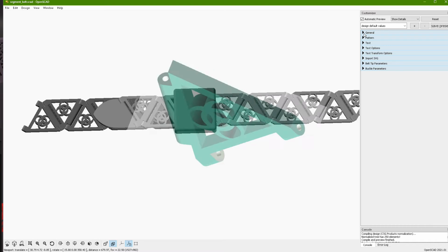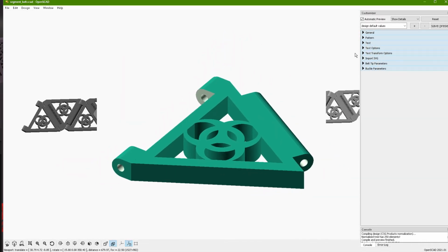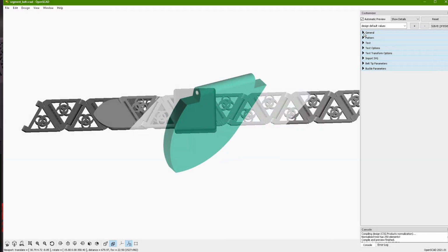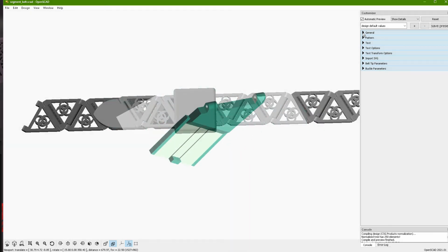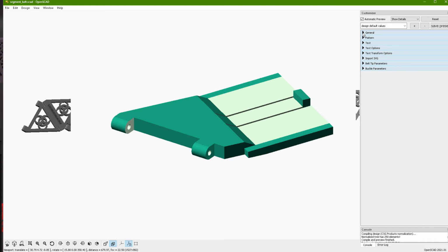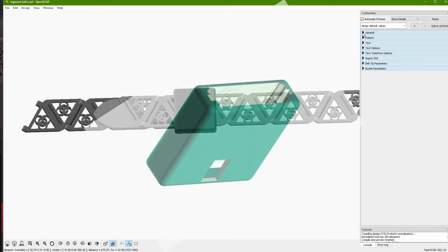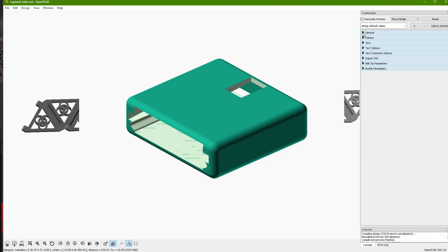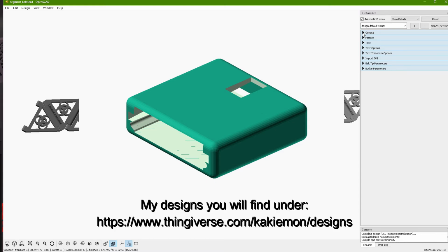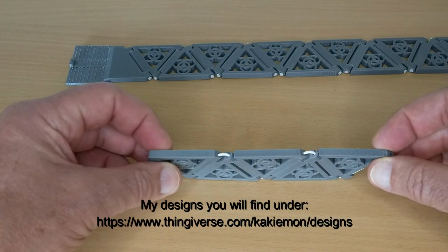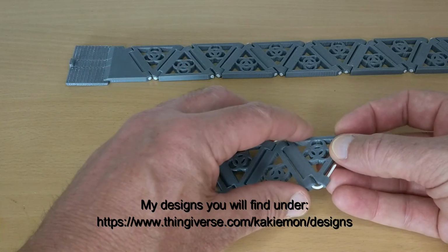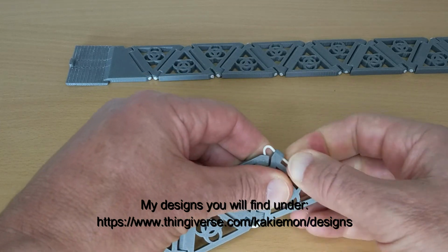A belt always consists of the following parts. First, a variable number of belt segments. The shape, size and pattern content can be modified within a big range. Second, the belt tip as the last segment in a chain of segments. Third, the inner buckle that is mounted on the opposite side of the chain belt segments. Fourth, the outer buckle that is used to connect, to lock and cover the belt tip end together with the inner buckle. Fifth, a string or individual hinge pins that bind all belt segments and function as hinge rotation points.